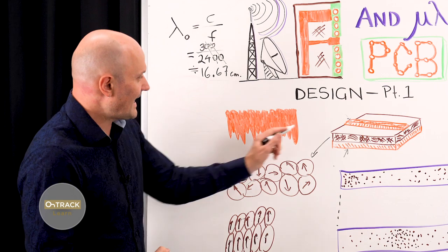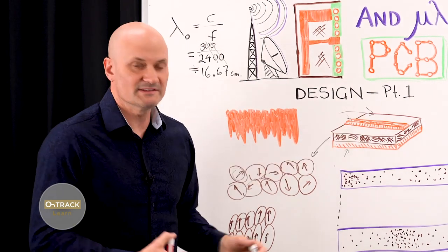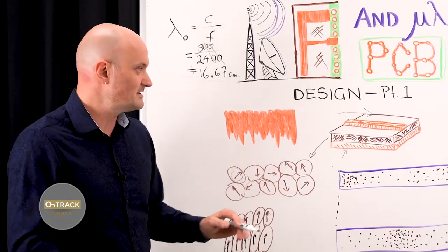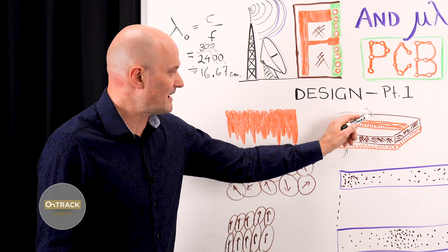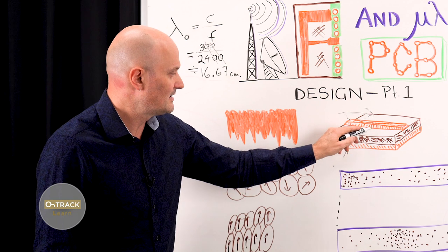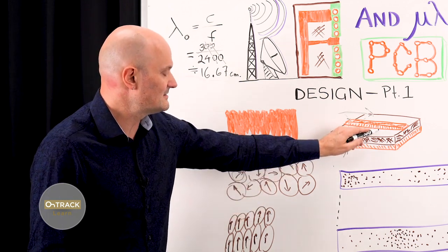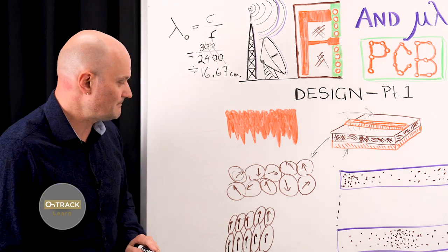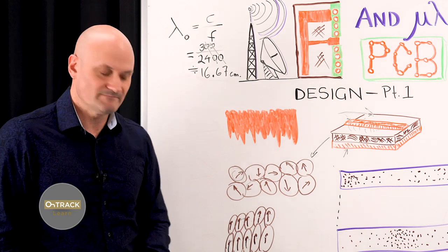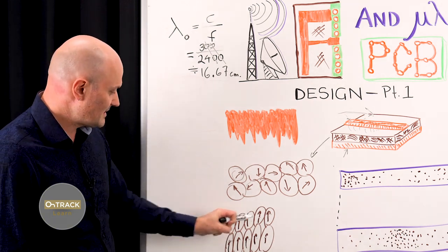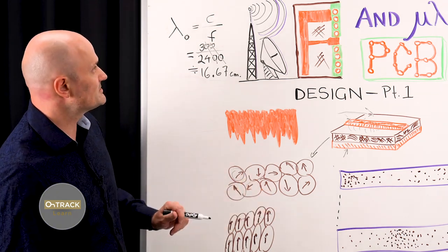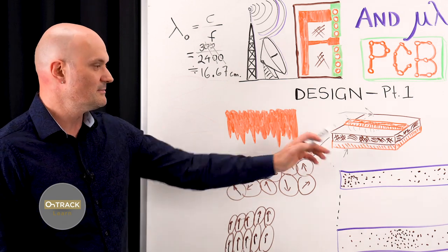And so as a signal travels down this trace, and this is for any kind of digital signaling as well, not just RF and microwave, but also pulses in a digital system, as the voltage travels down at a finite speed down this trace, it has to charge those domains in the insulator between the trace and the reference plane. Okay, so that takes time. Unlike a vacuum, that takes time and effort, and so that time and effort to orient these charges gives rise to a different propagation velocity in the material of the substrate.